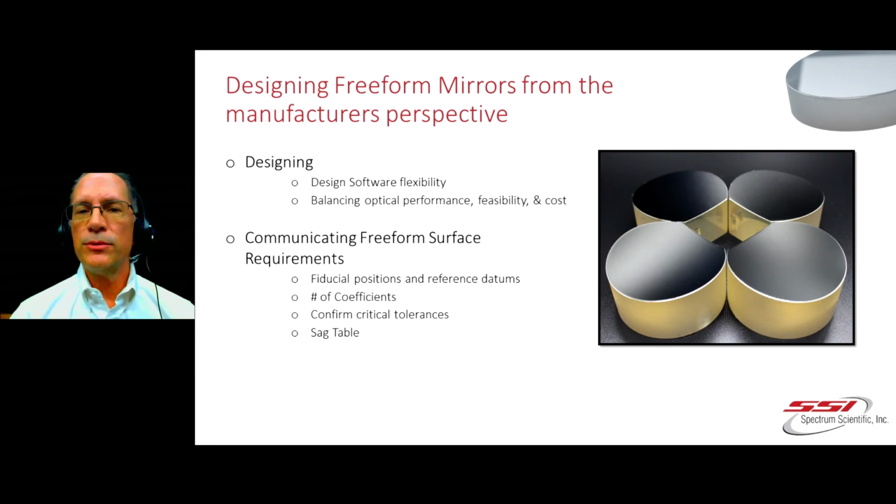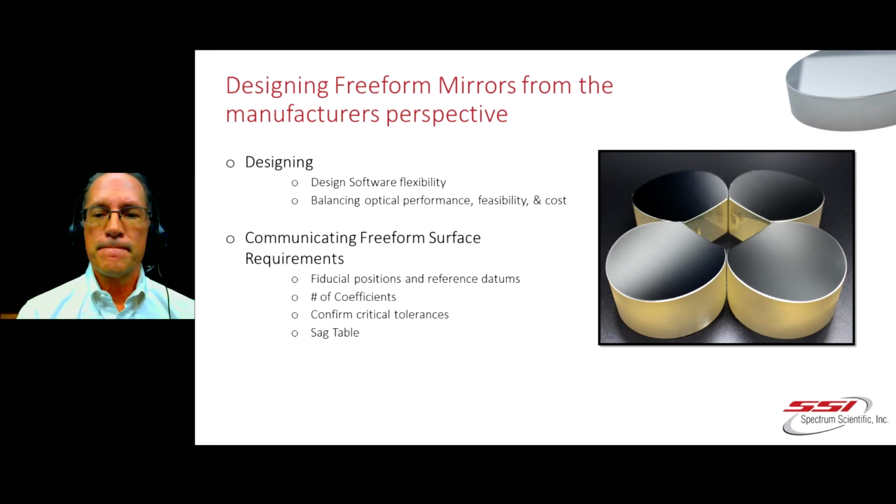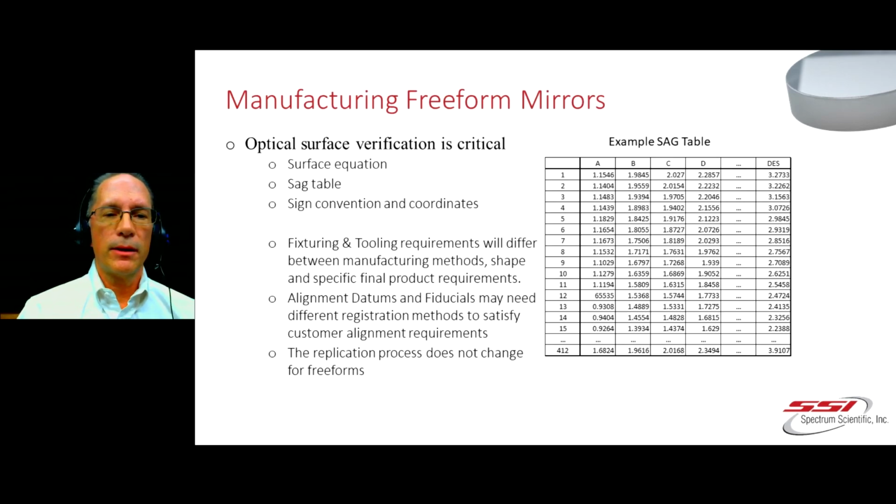With that said, the truth is, in all the freeforms I've seen for imaging application, it's just a few microns of departure or less that's required to make the corrections you need. So these don't need to be drastically crazy shaped mirrors. But once you get your design in hand, it's really important to start talking to the rest of your team about the optomechanics, and other aspects of how you're going to integrate the freeform mirror. And I'll move on to the next slide.